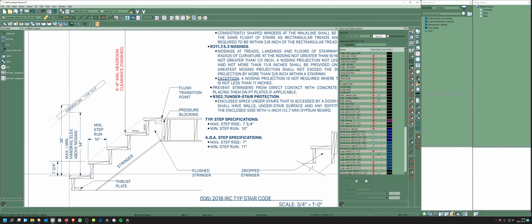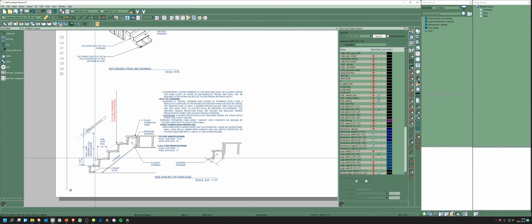If you were going to do hardwoods, I would notch all these nosings off, and then you would go with your riser up to here, and then your oak tread or whatever out over. But you'd have full gluing, screwing, whatever. You could even come in from underneath. You could put heavy weights on your oak. Instead of pin nailing from the top, you could glue these things, put some weight on them, and then from underneath screw with the right depth screw, go up through here into the oak and pull it tight. So there's lots of cool ways to do that. I'm not a finished carpenter though, so there's that.